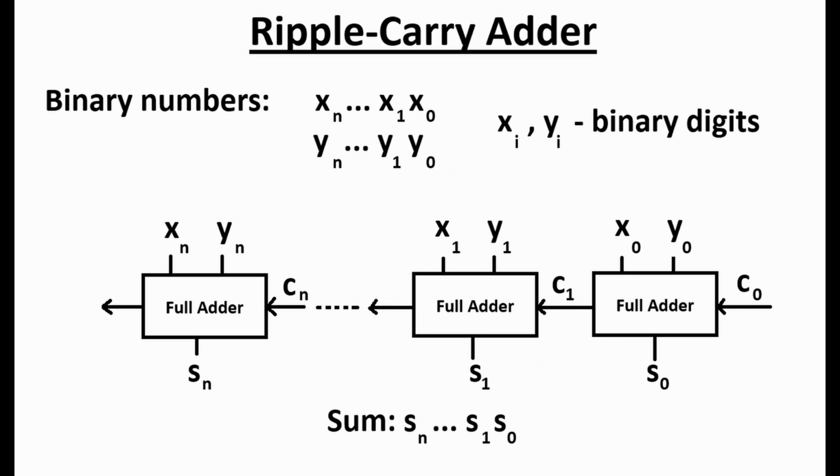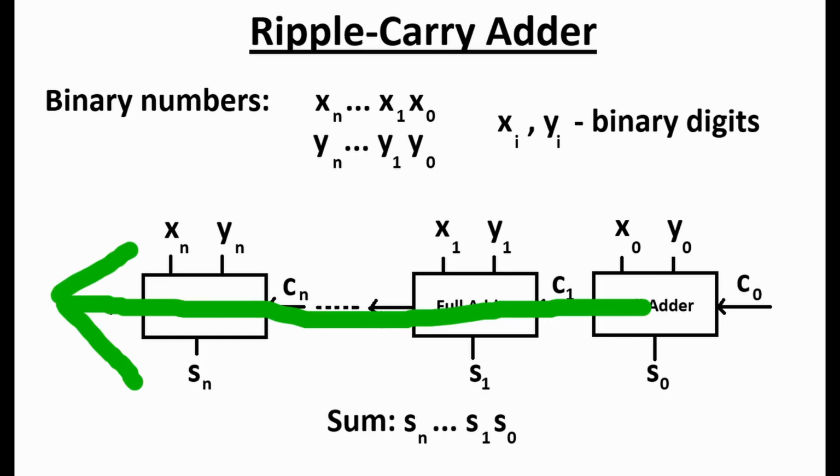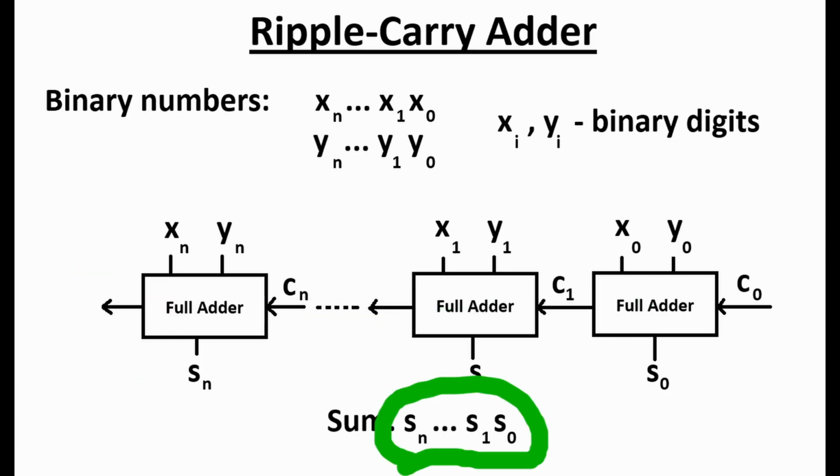Much like when we add 2 numbers on a piece of paper, we sometimes have to carry forward to the next digit if the number is too big. This same procedure is then repeated again at the next full adder and continues. Hence the name ripple carry adder, as the carry out bits ripple through the adders until we ultimately get to the final answer.